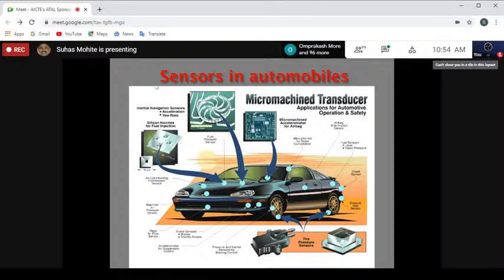And you should start this from your own institute, because as you know, when you work on small projects such as making a robot, you have to get hold of an electrical person for choosing the right motor, the servo motor or stepper motor, and then you must find out what is the torque required. Then you have to get into the mechanical domain and see how much friction will have to be overcome, and what is the leverage, and what is the torque that I will need, and whether my motor will be able to negotiate that particular torque. So this thought process begins when you start working with